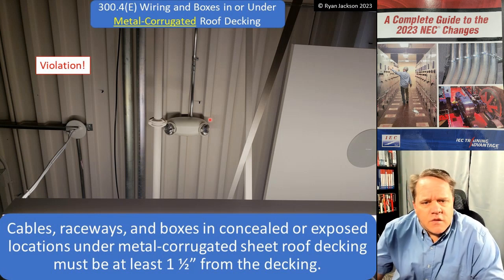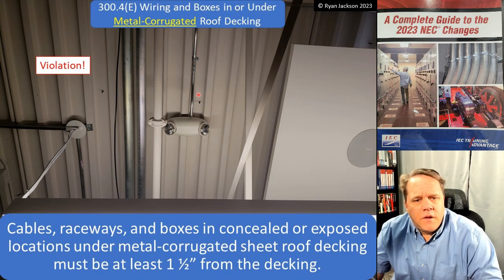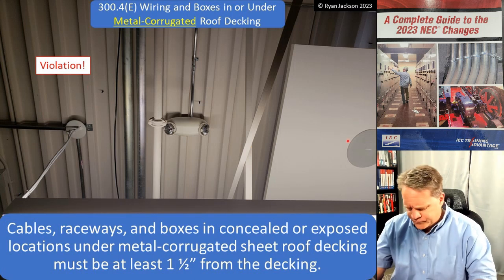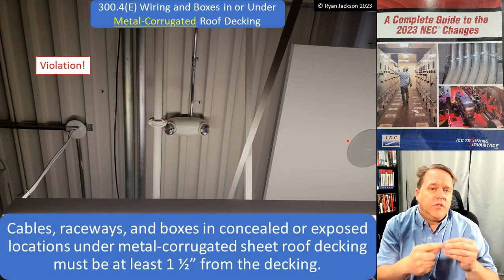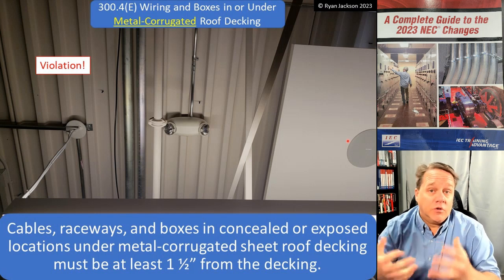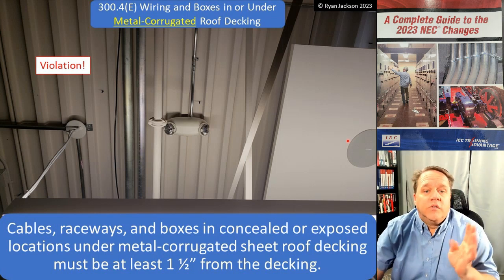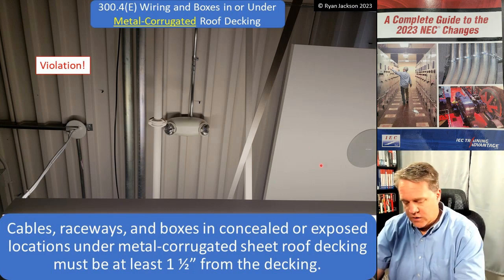We can see these roof decking screws that just barely miss the EMT. One I'm circling, and then we've got one over here. Those roof decking screws are a good 6-8 inches long. They're self-drilling, self-tapping. They are nasty, nasty screws, and they will go right through a conduit. So we added this language back in the 2011 code, and I think for good reason.